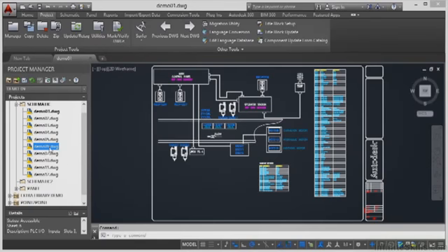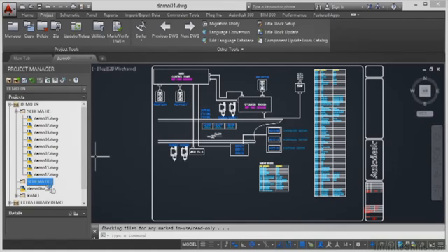What I do is I click, drag, and put it underneath Schematic 2 like that, and release. And you'll see that that then moves. Now, it hasn't moved exactly underneath. It's actually gone into the Demo 09 folder. You need to be careful how you drag. And you'll see there that if I then position it over Schematic 2, it then goes into the folder. So it's not a case of drag and use the little black line underneath. It's a case of drag and place it over the folder. Very much as if you were working inside Windows Explorer.